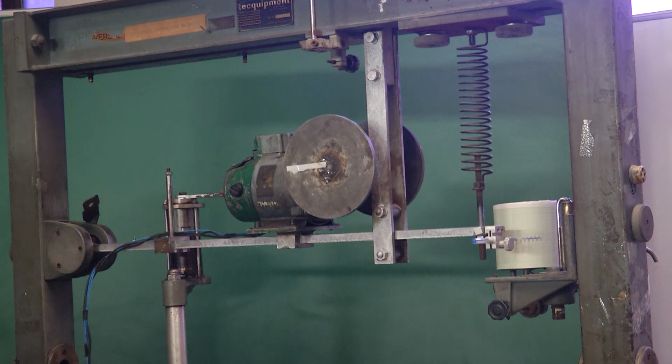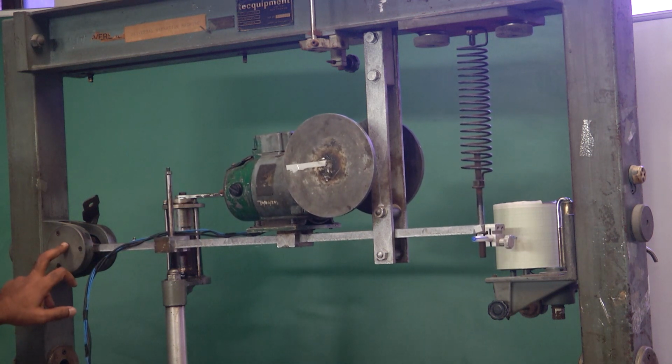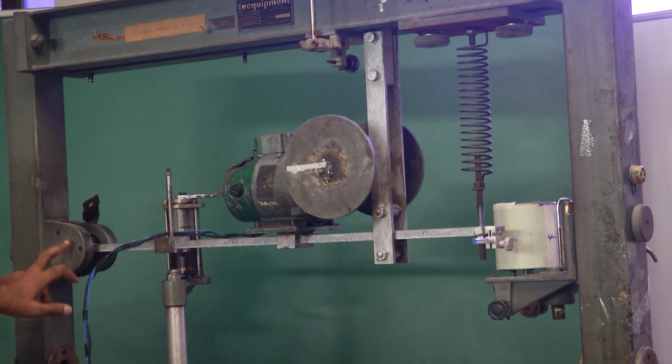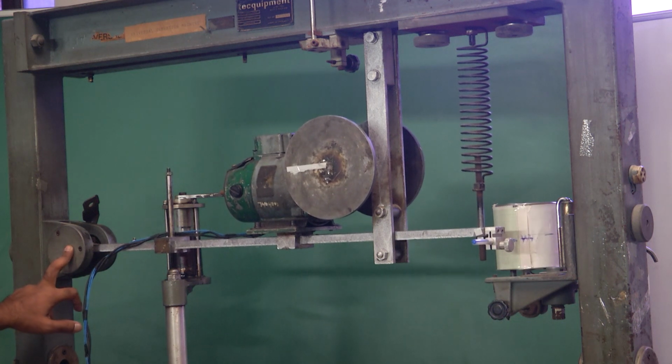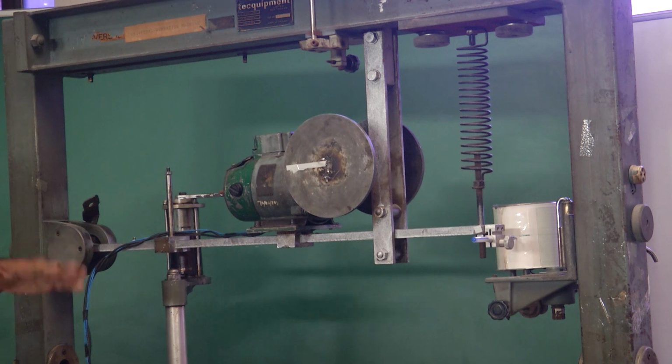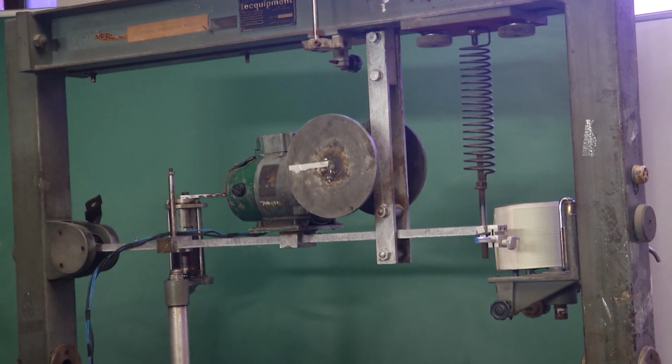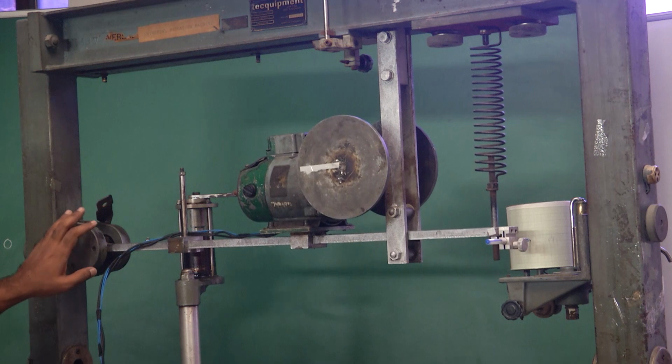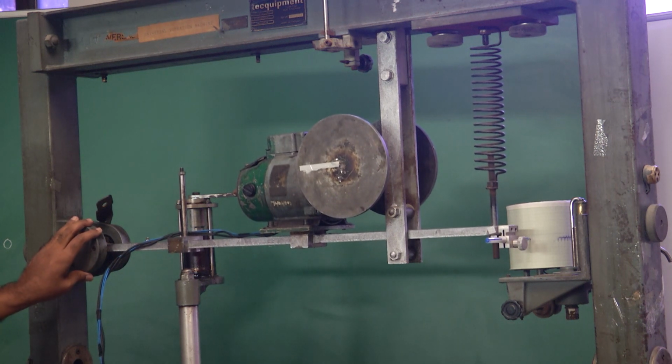The other possibility is the hinge, because the hinge is in the form of a bearing. At the bearing, because of the relative motion, there is likelihood of some energy getting dissipated. The friction at the bearing location, however small, is going to cause damping, converting the vibration energy into heat.